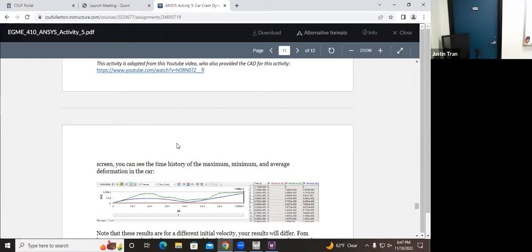Yeah, but for the last one, you're going to have to do some operating too, because basically what you want is a transformation matrix of the two ACSs. So you have ACS upper and ACS lower, because everything you did here was for the lower body. So this is ACS for the lower body, and what I've given you in part 4 here is the two transformation matrices for the upper arm, excuse me, lower arm, upper.